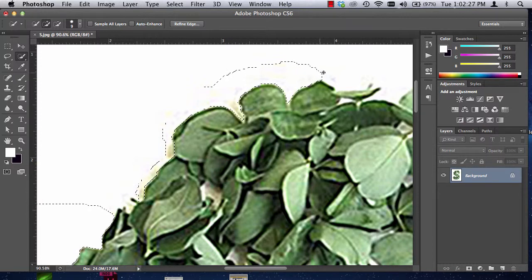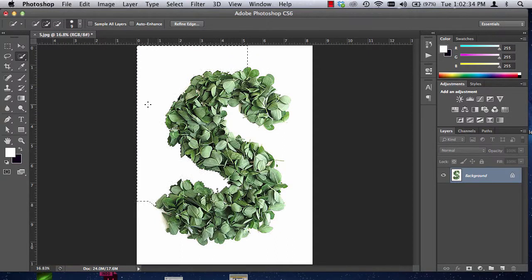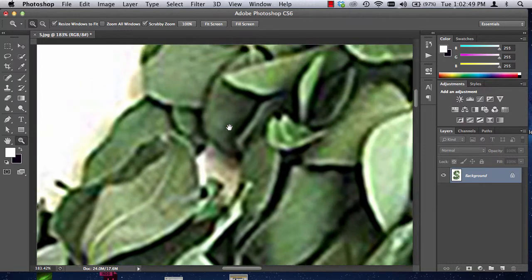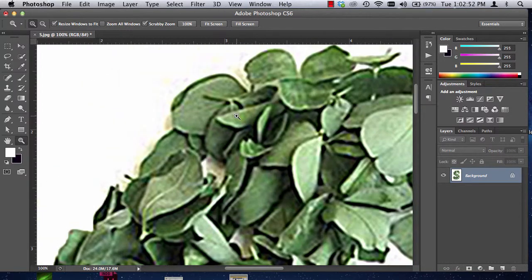So here I'm seeing some noise outside of my image, and so I'm clicking and dragging around. Now I will zoom out to see how much of this it has grabbed. If you don't like what it's done, hit Command Z. If you don't want to add to an image and you already have stuff selected, hit Command D to deselect. I'm going to zoom back in, move around, and maybe do this again. I'm hitting Command minus to zoom out just a little bit. So I'm going to go in through here and I'm going to paint around the areas that I need to get rid of.